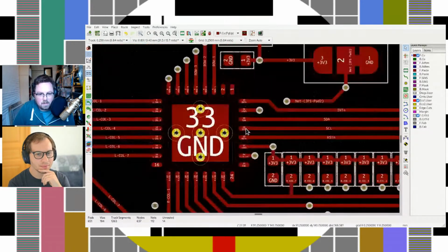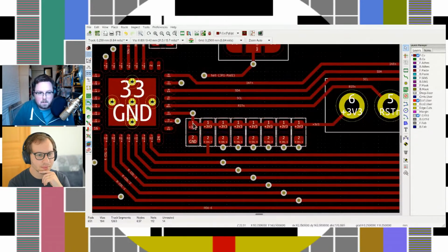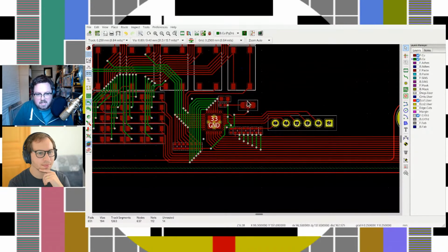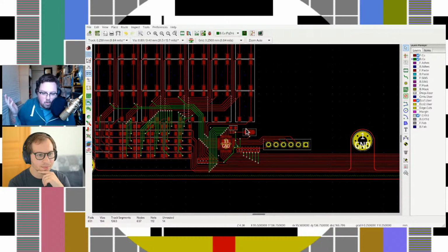And you'll end up picking up little tricks like, okay, I need pull-ups, so I can put these all on the voltage bus with connections here, and figure out nice ways to hop between 2 different circuit levels or things like that. Because if you can do 2-layer boards, they're cheaper, and you can pick fancier colors, because JLC will only do assembly on 2-layer boards in any color, or 4-layer boards just in green.